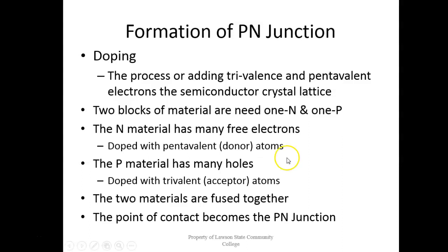What an atom will do is go through shells, but we're talking about the outermost shell of an atom. This is referred to as the valence shell. What's so important to us is that the valence shell determines the conduction characteristics of the atom. Is it a good conductor or a bad conductor? Or is it in the center?